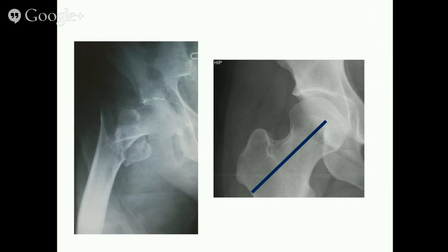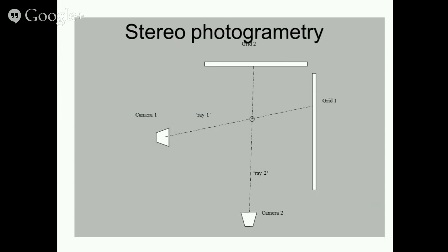However, what he did was he took a technique, a medical technique from X-rays called stereophotogrammetry, where you sent two X-ray beams across the subject to plates on the far side of the wall, and from that you could triangulate where features were on the X-ray. So it gave a three-dimensional measure of objects in space from two perpendicular cameras.